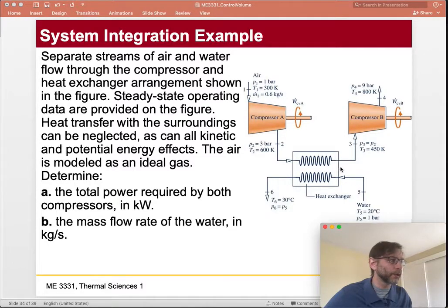So this is called intercooling. Sometimes in really fancy cars where they have big engines that have different stages of turbocharging. I don't know if you know anything about turbocharging. If you're a motorhead like me, you know what turbocharging is. Essentially, you're compressing the air before you put it into the engine, okay? And in this case, if you had a two-stage compressor like this, where you had one compressor and then a cooler and then another compressor, you can get really high pressures while still maintaining low temperatures, which is something you want. 800 K is not that low, but okay.